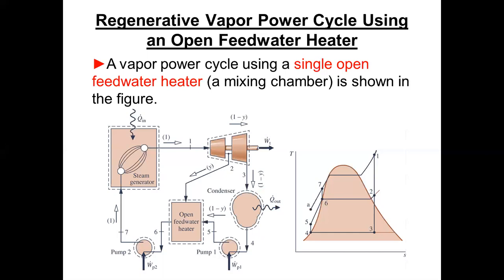You can look at all of this, and you should study it on the TS diagram. So 1 is up there. So now we're showing superheated steam at 1 at the high pressure, the high isobar. And so we're showing an isentropic turbine here, right? Because we're dropping straight down from 1 to 2. And so that enthalpy difference, H1 minus H2 times the full mass flow, is going to be the work that's generated in that section of the turbine.